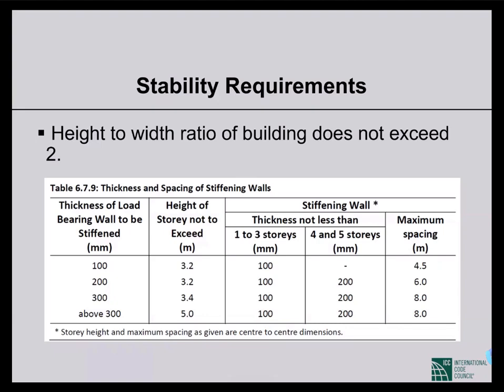If the contribution of walls to take axial load in an RCC frame is to be considered, what things to keep in mind? Can we think of bypassing some load from columns to walls? If that is so, what construction method is a must? I addressed this issue at the very beginning. It is very, very risky to consider gravity load taken by masonry walls in RC frame construction, because they are incompatible from the point of view of flexibility.